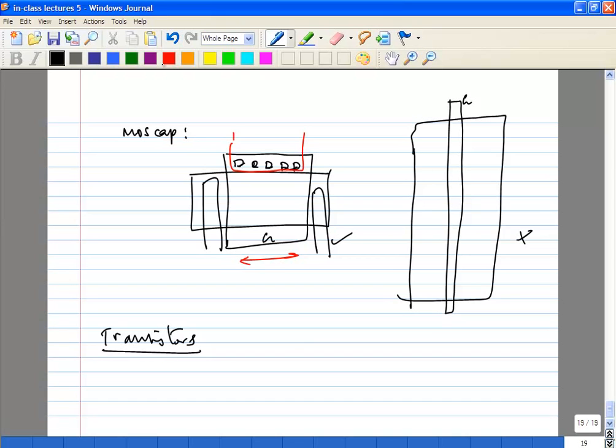do your floor planning. For example, this may be your signal, but the extra space you have may only be here. Why? Maybe your signal input is coming here, output is going here. You could perfectly well have a case like this. So if you have something like this, where would you place the bias? You can split the bias transistors. As long as they are laid out in an array here internally, you can have some decent matching. You don't want to spread it out too far, but you can work around it. Or for example, you may split your bias like this. This may be cap. Cap, you can spread it around, and that's usually perfectly fine.